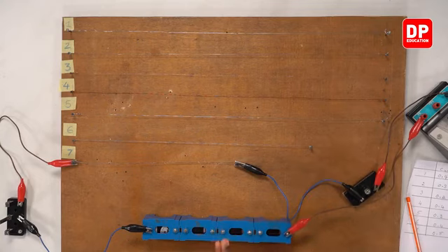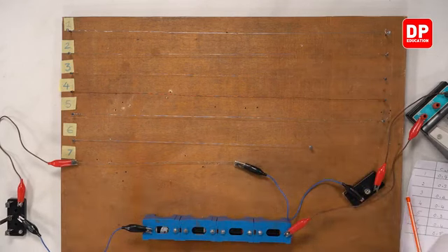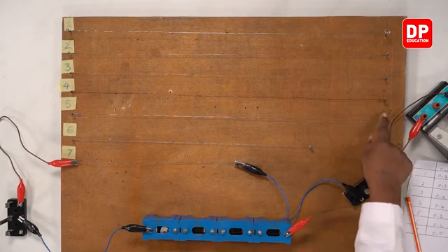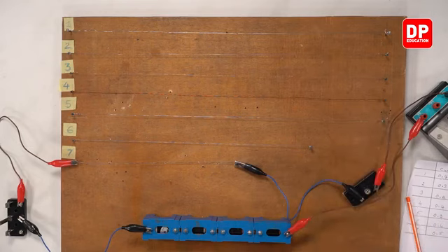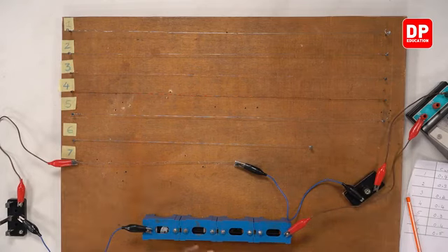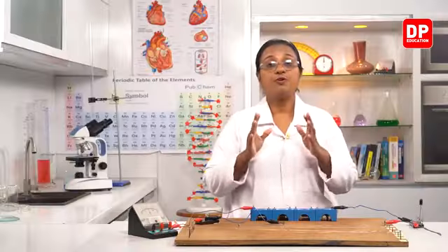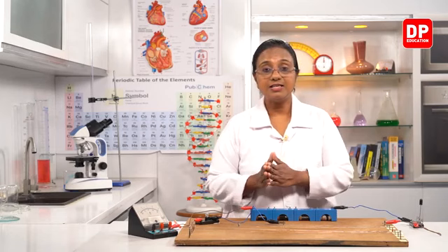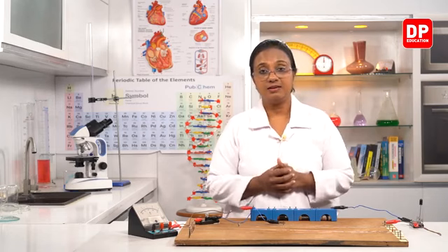length is different. When the length became shorter, the shorter wire, the brightness was more, current was more. That means when the wire is short, the resistance is less. The longest wire, less current, 0.3 amperes, and the brightness was less. That means the resistance of the longest wire was the highest. So from that you all can understand, when the length of the conductor increases, the resistance increases.